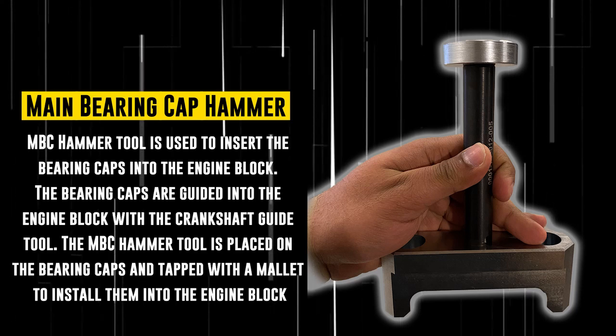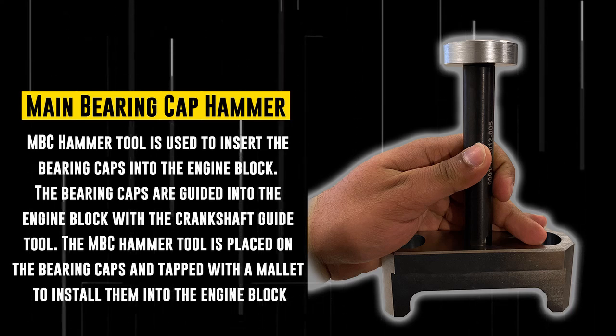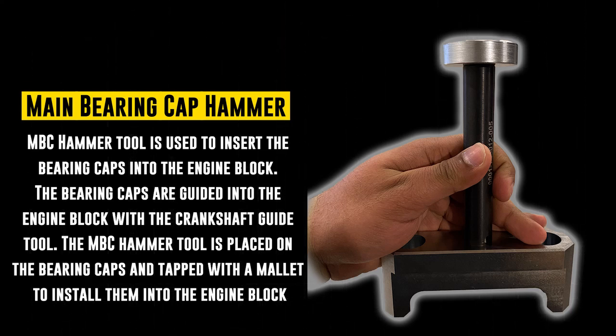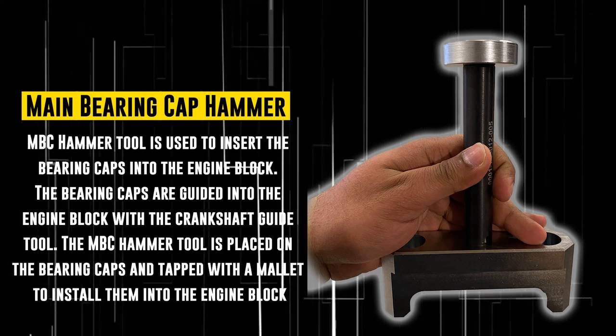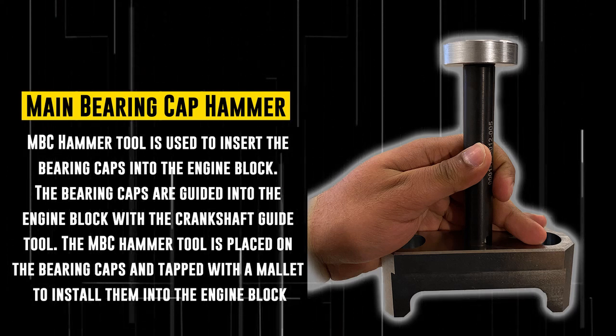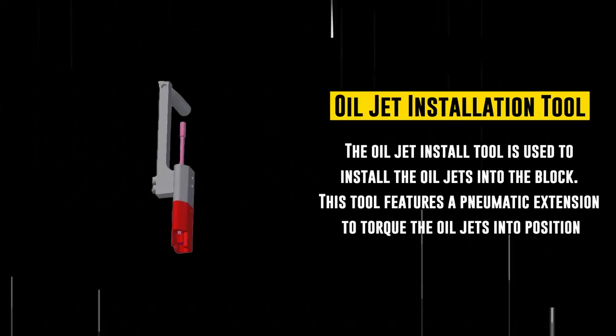Main bearing cap hammer. The main bearing cap hammer tool is used to insert the bearing caps into the engine block. The bearing caps are guided into the engine block with the crankshaft guide tool. The MBC hammer tool is placed on the bearing caps and tapped with a mallet to install them into the engine block.